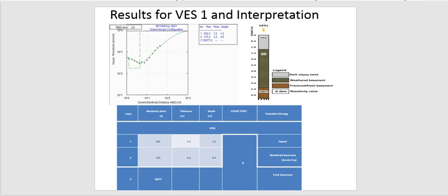Okay, so I think I need to take you down a little bit on this discussion. Since I've been talking about movement of water, and I've talked about the issue of permeability, I think I need to say something about permeability. What is permeability, and what can we actually say about it? Permeability is a property of a porous material which permits the passage or seepage of water or other fluid through its interconnecting voids. A material having continuous voids is called a permeable material.